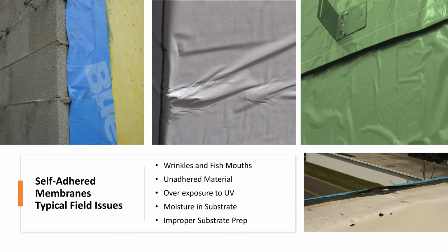So if I'm going to the site, I'm looking at the technical data sheet that says this has to be covered in 30 days from UV, and I'm going to go, when was this actually installed? And are we starting to go over what that limitation is?